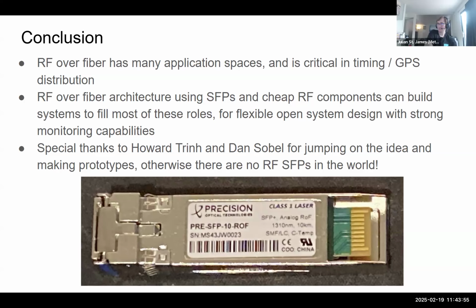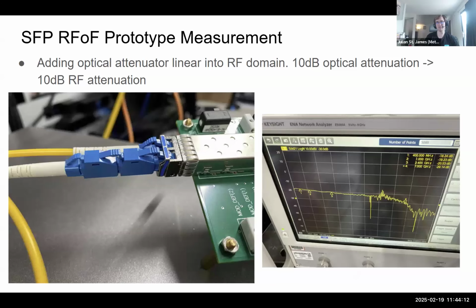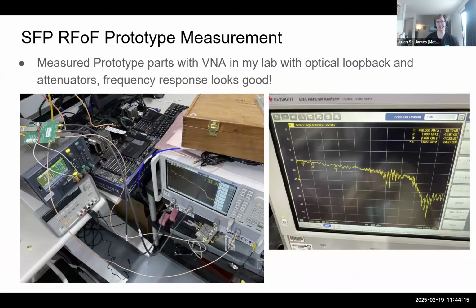Any other questions for anyone? When you looked at the signal linearity, you didn't notice any linearity issues caused by group delay problems? So this was my measurements of the SFP itself. It's not 100% flat, but I put the markers up at different frequency ranges. I think some of this is due to my cabling having non-ideal measurements, and the eval board itself is also not meant for RF applications. This is an SFP eval board for digital SFPs.